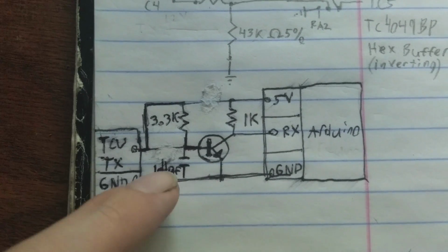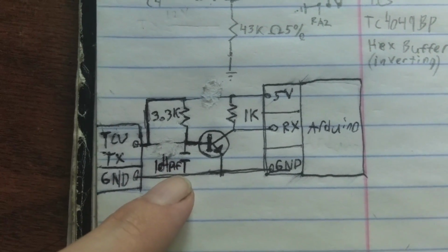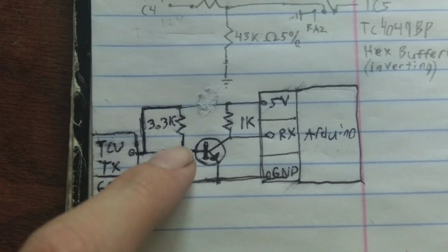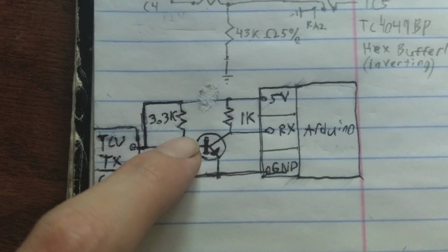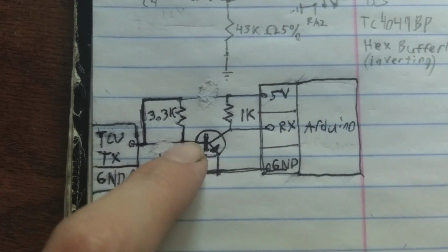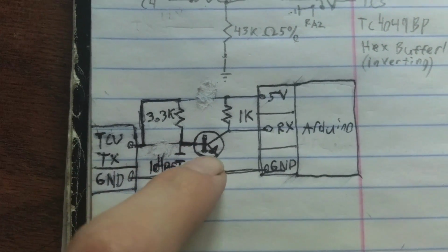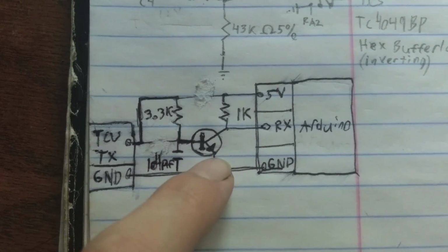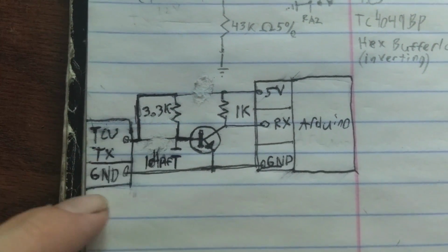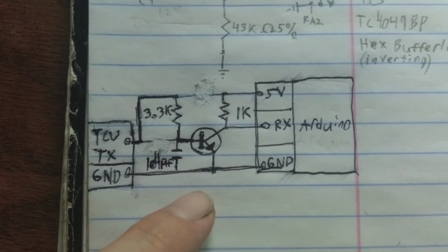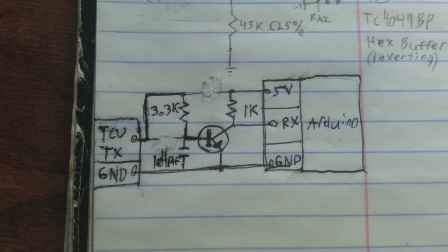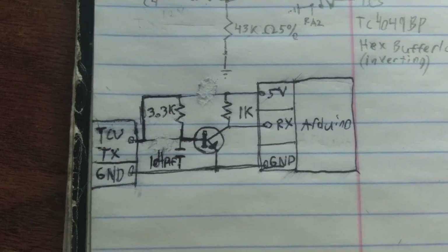So this kind of works. When it does work, it works. When it doesn't work, it doesn't work. So basically, we'll always get our signal here to ground, but it might not be enough voltage to actually switch the transistor, so sometimes this doesn't switch. So again, this might need to be a smaller resistor, or I might need to do an entirely different system to get this to work. But that's what I have so far, and it's kind of getting me somewhere.